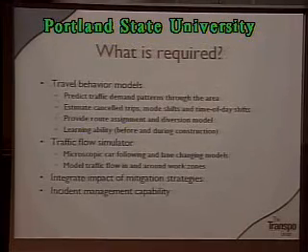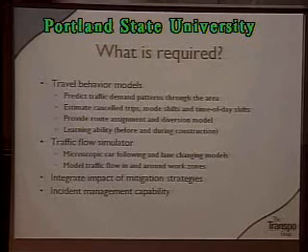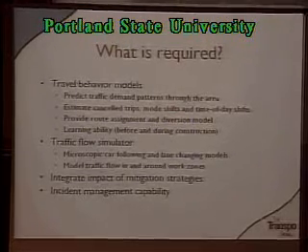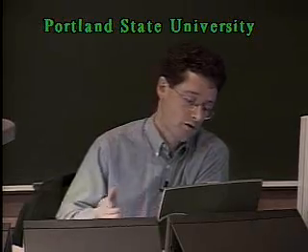What is required? A good travel behavior model, a traffic flow simulator to capture the impacts of the lane closures due to construction, and not only the impacts but also how people are going to react in front of these unusual conditions. Whether they have information before, during the trip, how is the system going to perform under different scenarios.